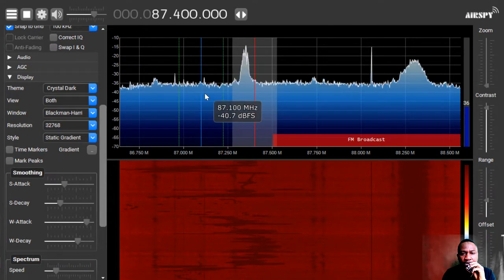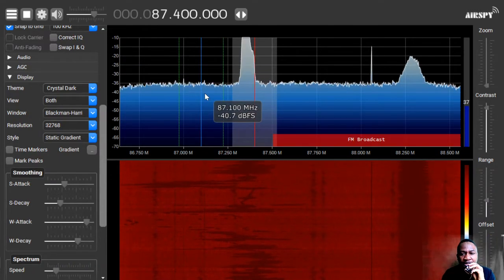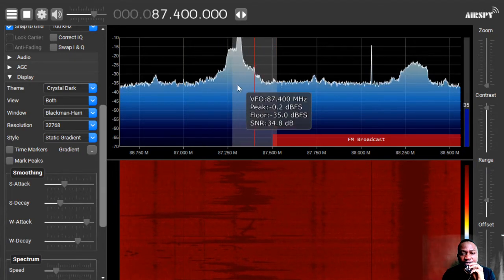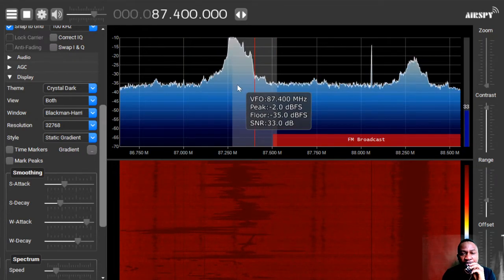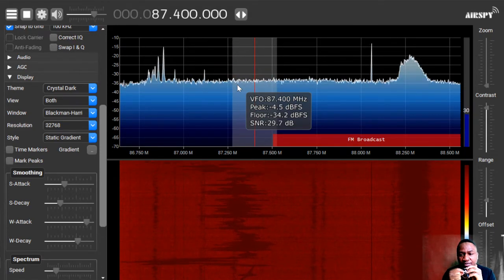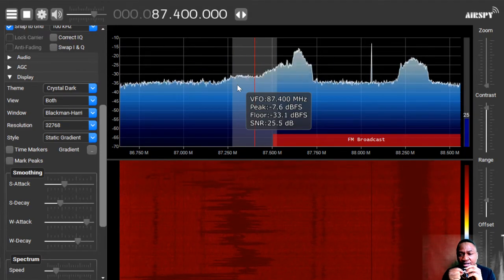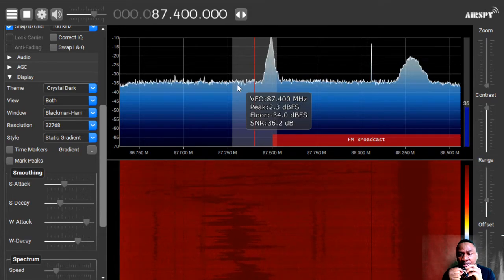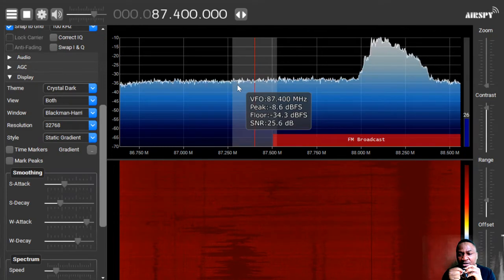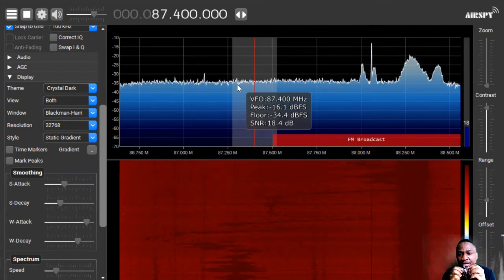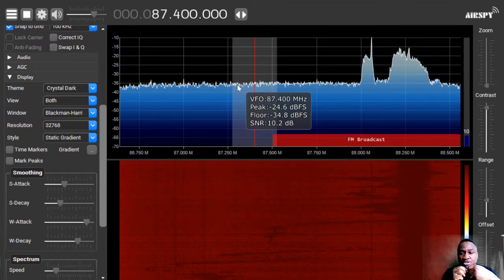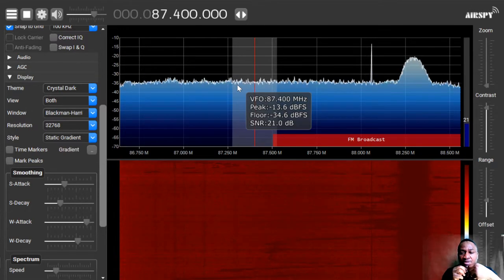Now, all right. As I come close, I'm affecting the value of the voltage. But anyways, you can see it's transmitting around 87.4 megahertz. Now I can change the value by just adjusting the voltage. As I change it, you can see it practically running. You can scan through the circuit by changing the value of the inductor, just change the length of the inductor.